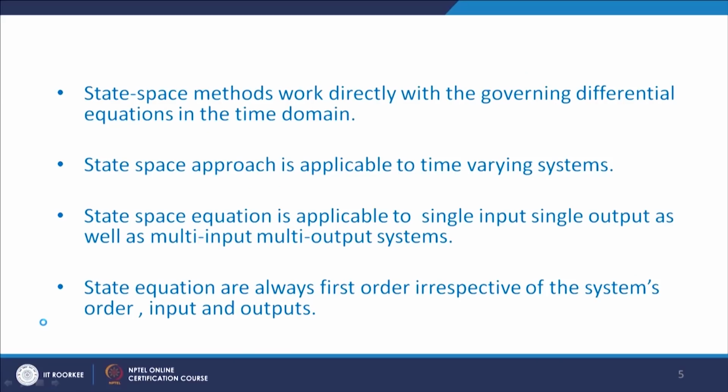Classical approach is based on transfer function approach, and you know that in transfer function we have to neglect the initial conditions. Whereas if you go for a state space approach, we can consider the initial conditions. Third, state space methods work directly with the governing differential equation in the time domain. As I told earlier also, state space approach is basically based on time domain, and classical approach is based on S domain or a frequency domain.